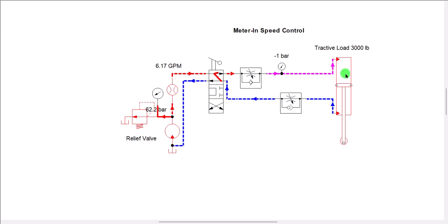and it creates so fast that the pump simply cannot keep up, and it fails to refill this void quickly enough with fluid. This results in a partial vacuum above the piston, and you can see the vacuum is measured by this pressure gauge in this line. So there's a depression in this line, which is clearly shown by -1 bar pressure. So it's a -1 atmosphere inside of the blind end of the cylinder. This is similar to what happens when we try to suck liquid medicine into a vaccine syringe by pulling down on the piston. Same thing is happening here.